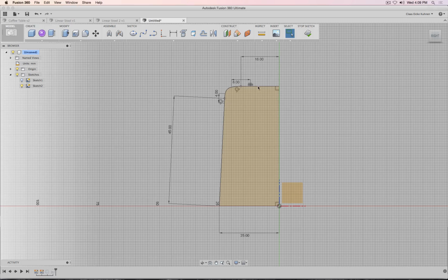So when I change the dimension, this endpoint moves to the secured line. The same here, we have a width, it moves to this point. And wherever these lines touch each other, they're kind of like magnetically connected to each other. And then the transition for the handle or for the fillet, we sculpt by having linear dimensions on the tangency handles.